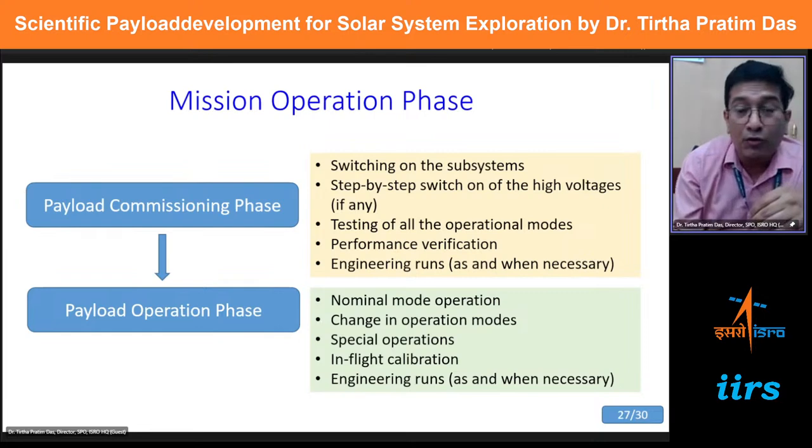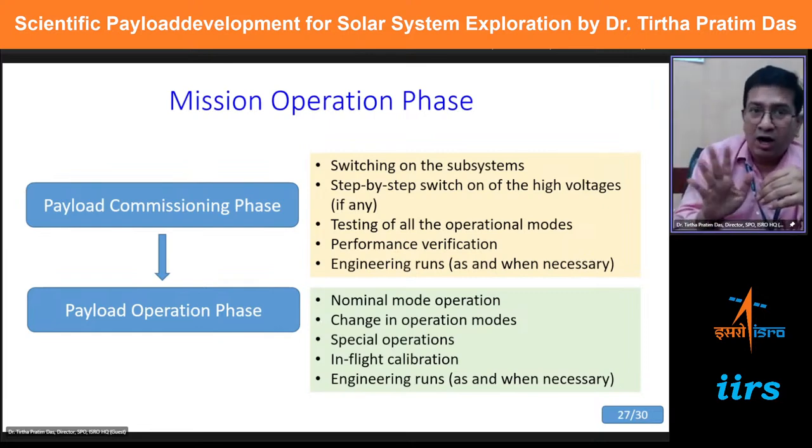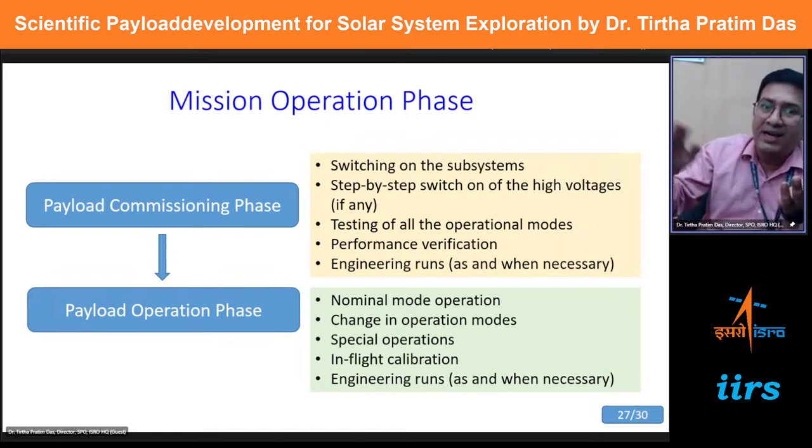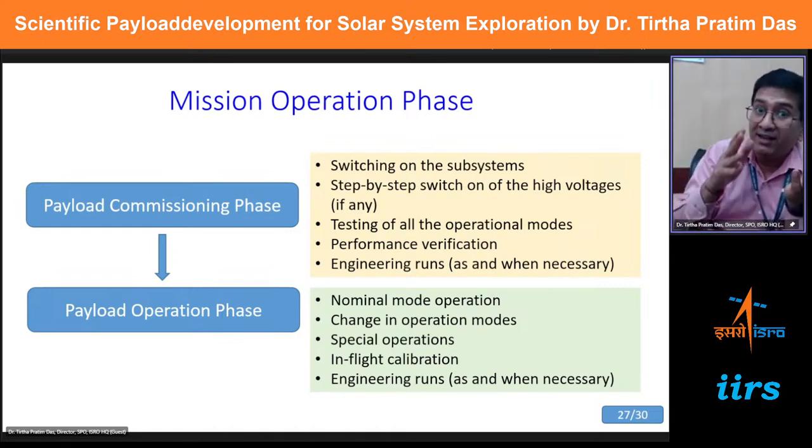Just remember how you're woken up. I don't know really how you're woken up, but children are woken up very gently. They are not woken up with a shake. They're woken up very gently, and that's how a scientific instrument is also woken up, made to wake up in steps by switching on the subsystems, step by step switching on the high voltages, if any. All of a sudden, 2 kilovolt, 3 kilovolt, 6 kilovolt, one should not switch on.